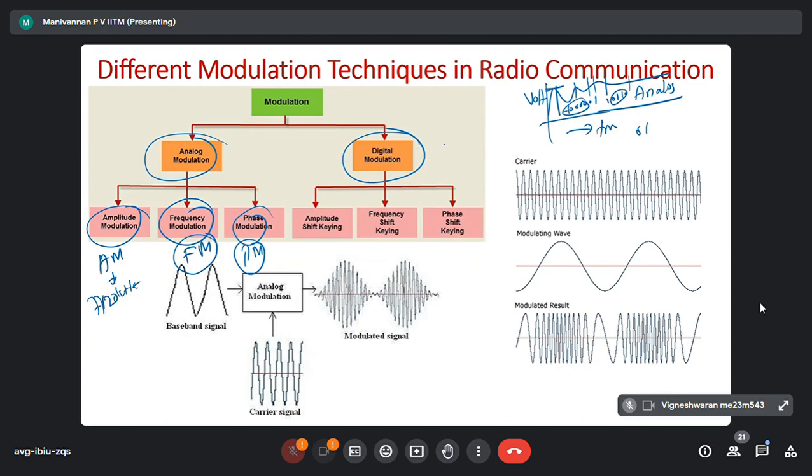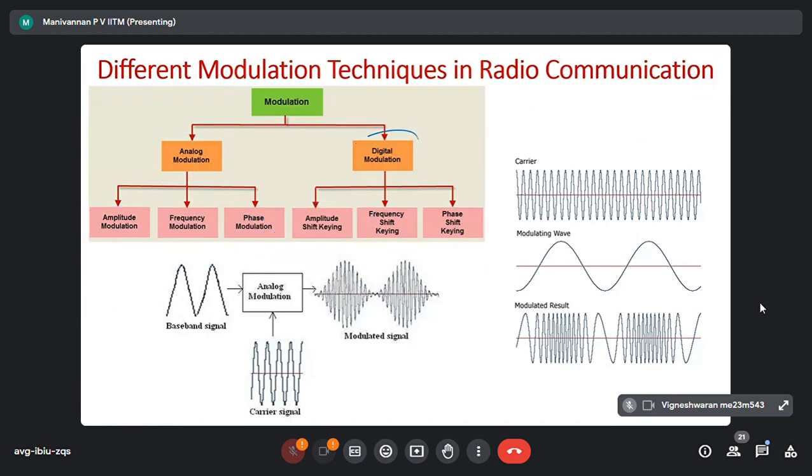After that, this binary data can be modulated. There are three types of modulation there: amplitude shift keying, frequency shift keying, and phase shift keying. Same as this. Right? It can be digital modulation, in which the binary data 0101, these bits I want to transmit. In CAN bus, all those things we send as 0 volts or 12 volts, correct? Or 5 volts or 2.5 volts on wires. Here we have to transmit this one. So this needs to be modulated.